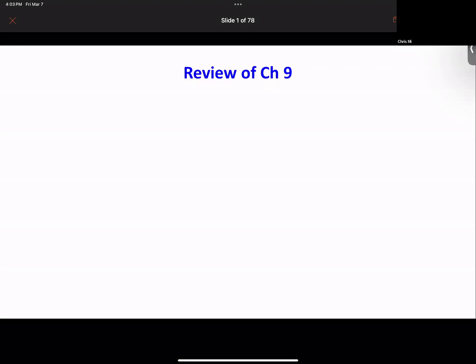And similarly, you can also use cascode, you can use current mirror load to increase your gain, to reduce the use of resistance, and so on. Okay, so that's your differential amplifier. Then within that same topic we talked about the range, like input range, output range, because you have to maintain these transistors in the saturation region for the MOSFETs or in the active region for BJTs. That will limit your output and your input. And for MOSFETs, we had examples showing that your input can be as large as the voltage supply. That's called rail to rail. So we got this common mode input range and common mode output range. So we talked about those.